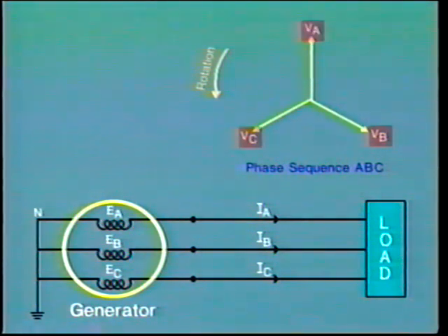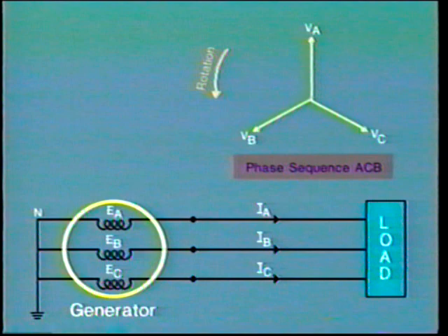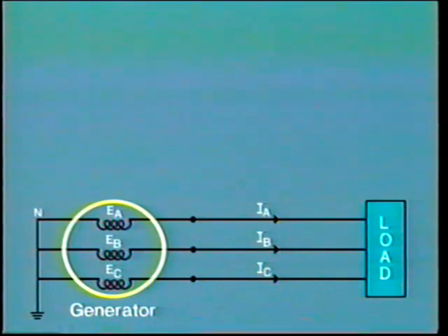The three equal phase to neutral voltages are shown, and by convention, they rotate in the counterclockwise direction in the sequence A, B, C. Although this is the conventional sequence of phase rotation, be aware that some power systems are connected to operate with the opposite phase rotation sequence, that is A, C, B. Keep a lookout for this item on drawings and schematics, especially when working with neighboring utilities.